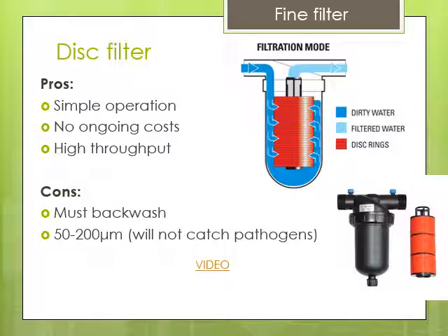But what it is, the water comes in on the outside of these, goes around the outside, and squeezes through a stack of plastic discs. These are hundreds of plastic discs stacked together. There's a mild amount of pressure put on them, and the discs have kind of a rough surface. So you can imagine that the water has to squeeze through each of those plates. So here's your water coming in. It has to squeeze through the plates to get to the center and then exit out the filtered end.